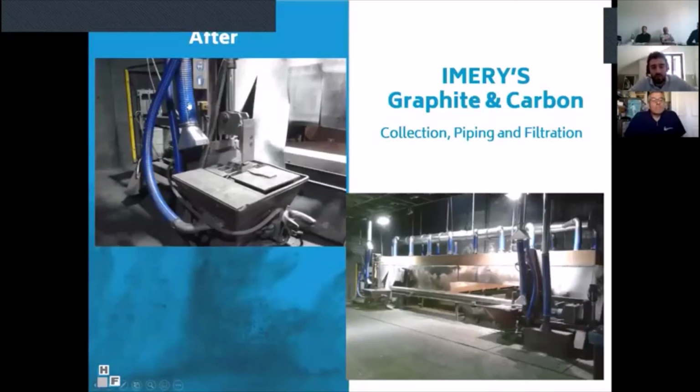We installed hose piping of high thickness, I think 15 millimeter for this blue piping, made just for very abrasive material. We redesigned all the collecting piping on the existing suction hoods, and we also made an environmental cleaning with very big hoods in the roof of the building.